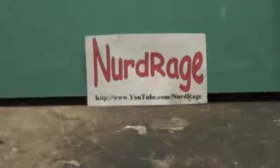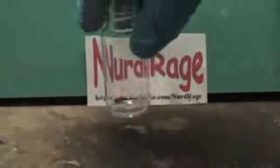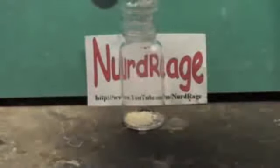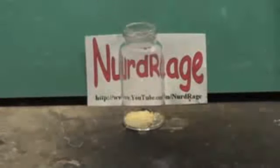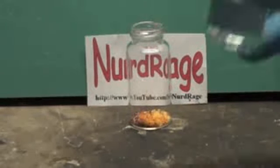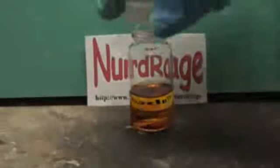Now we need to make the electrolyte solution. First start with 127 milligrams of pure iodine crystals and add to it 830 milligrams of potassium iodide. Already you can see it reacting to form brown potassium triiodide. Add 10 milliliters of anhydrous ethylene glycol and mix until it's dissolved.